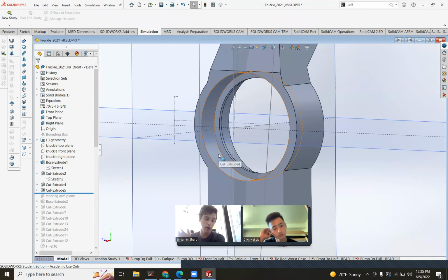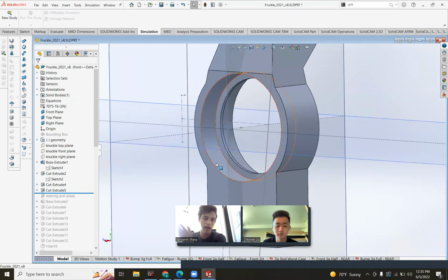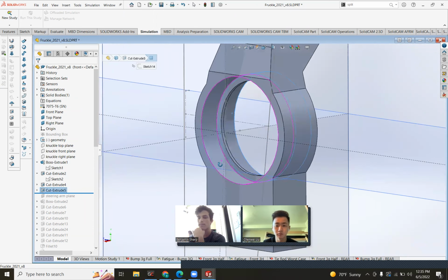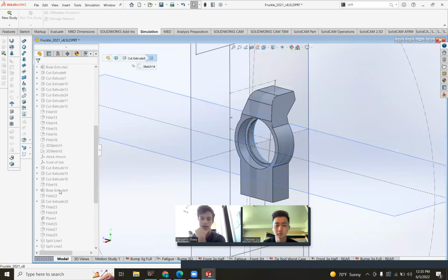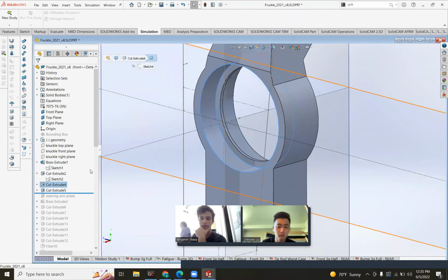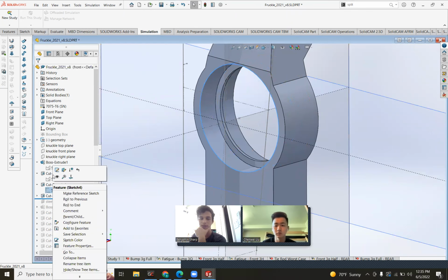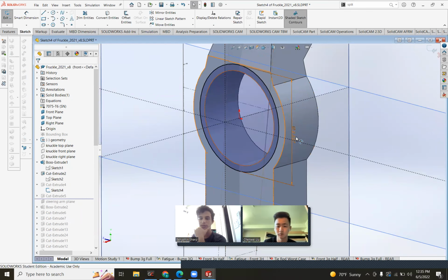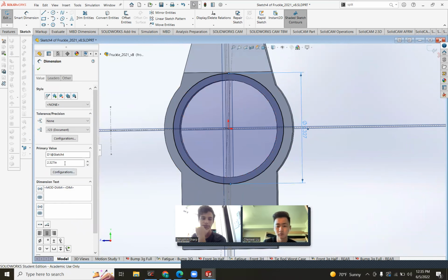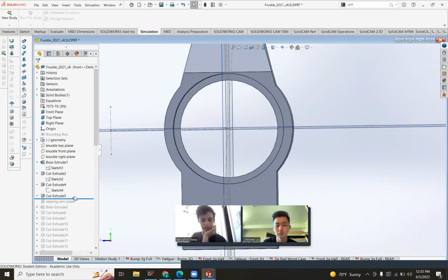Then you cut. You don't have to do this next, but then I cut, or Hannah cut. I don't remember who did each design step. Hannah did a lot of this, but I also did a decent amount of this. You cut away where the bearing sits, and these dimensions are very precise, given by press fit tolerancing. So this is exactly what it needs to be as long as we use the same wheel bearings next year. And then you can add the steering arm.